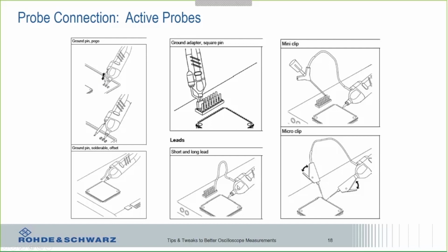Now again, sometimes you don't have a choice. If you don't have a choice, it's fine. Just know the limitations of using some of those longer leads and how it might affect what you see on the display of the oscilloscope.